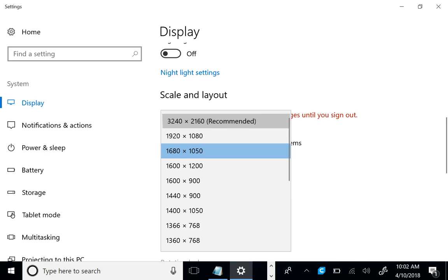If I change the infill density back down to something more reasonable, like say 10%. Oops. 1%. Okay, if I change it back down to 1%, it's one line. Yeah, so I hope it holds together. It's probably fine on this shape. It depends a lot on the shape, right? If I set it to 10%, it'll fill this with some kind of little grid.